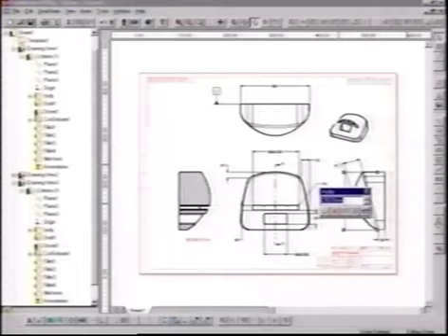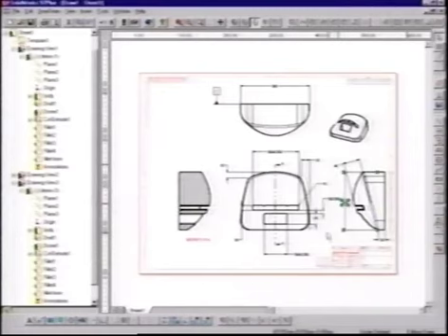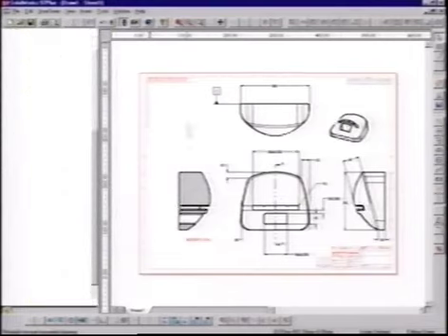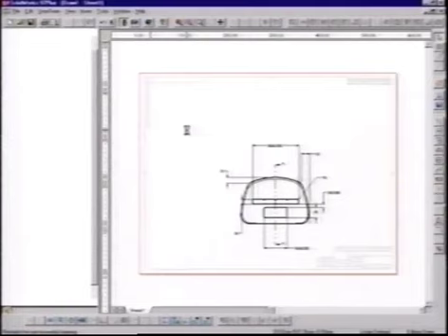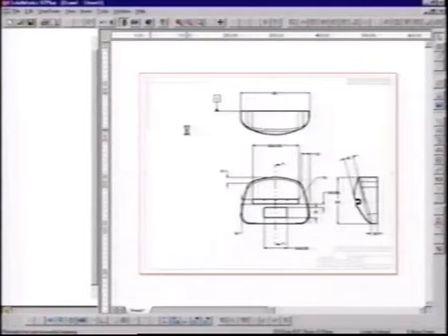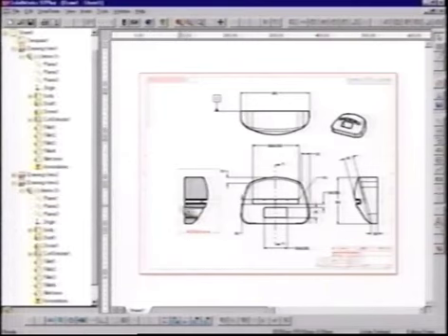So we're looking at our part, and we've been told it looks a lot like Rosie, the robot from the Jetsons, so we want to make some dimensional modifications so it looks a little bit more serious, because this is a serious exercise machine. What Joe's doing right now is changing the curvature of that dome feature by modifying its dimension. He's also changing the top height of that to make it a little bit shallower. When he makes that dimensional modification, watch how all the views in the detailed drawing update to reflect that change.